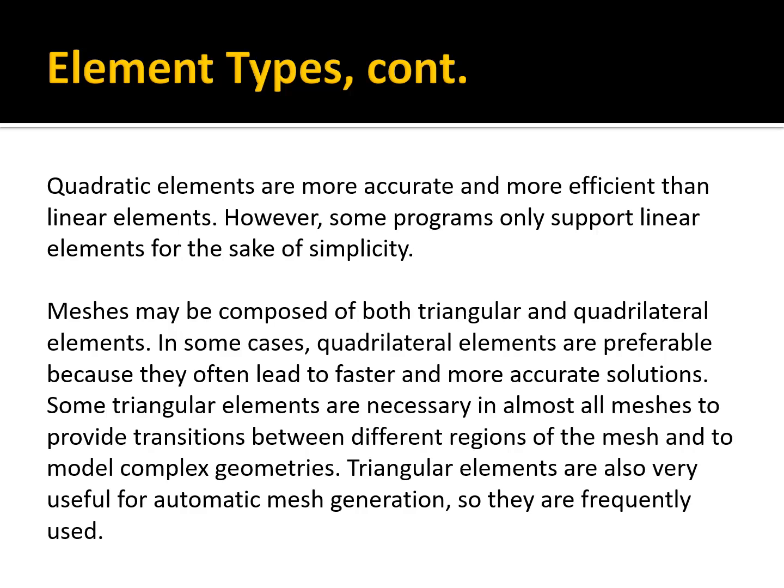In this course, we're going to use the GMS software and SEEP2D. And all we have to do is define our boundaries of each material, and it's going to fill in the interior with triangles. And it happens almost instantaneously. It works beautifully. And so we often end up using just linear triangles.